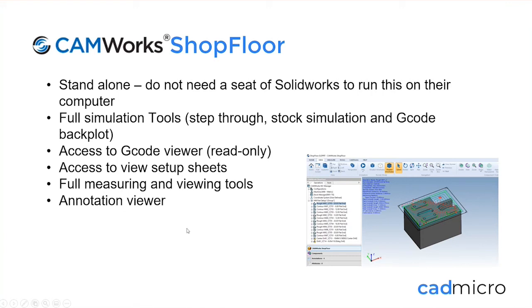We have access to view the setup sheets in here. So if you create setup sheets inside of CAMWorks, we can open the setup sheets directly from this package as well. Full measuring and viewing tools. So basically, if there's any dimensions or GD&T on this part, we'd be able to rotate the actual 3D CAD model around and see all of those features.